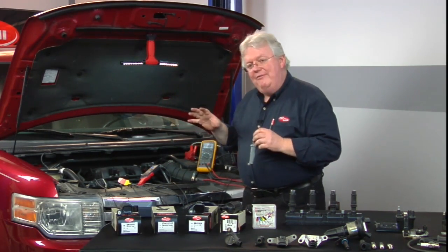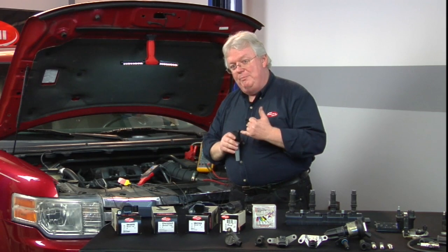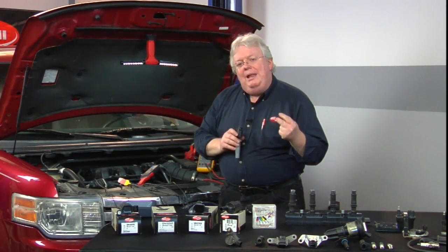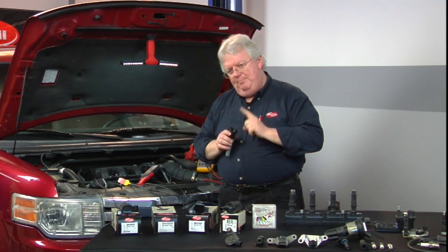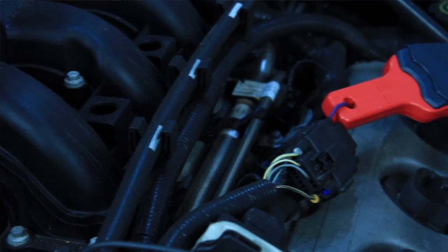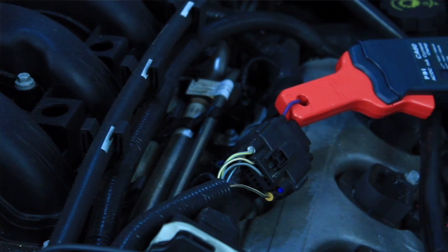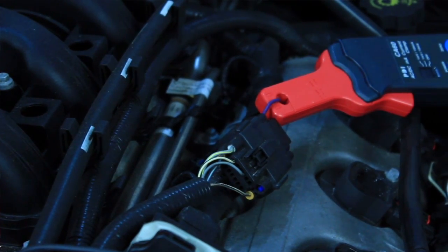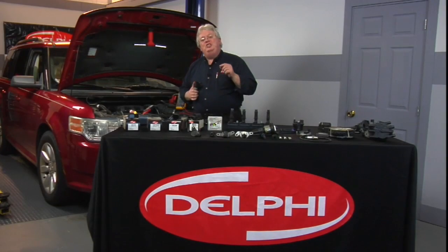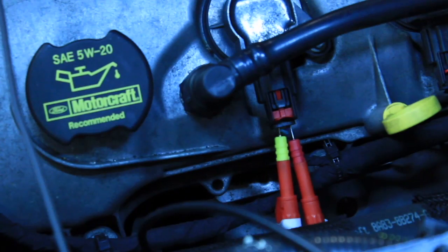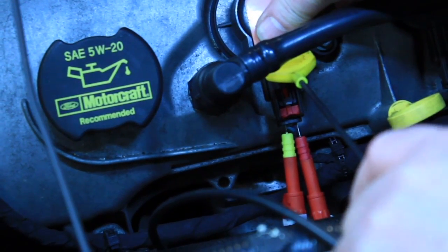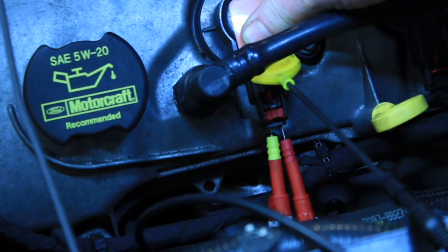And that's channel A and B. Channel A will be my power, that's my blue line. Channel B will be the ground supplied when the PCM wants the coil to fire. Channel C is going to be an amp clamp, which we already installed right here at the big breakaway connector. That's the purple wire to all these coils in the front bank here. And then channel D is going to be a little inductive probe, very inexpensive, maybe $100 or so. This guy lays on top of the coil.